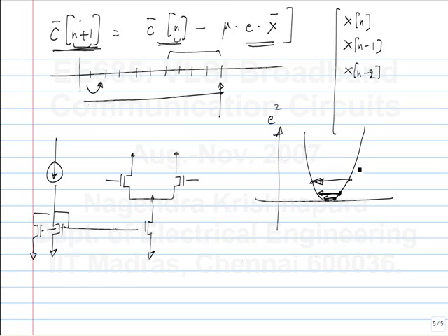Yeah, so you can do that. But what is the limitation there? To reduce the value of mu, you simply have to have more steps, right? Because in this case, I go from having one transistor to two transistors, three transistors and so on. So the step size is limited by how many pieces I have split this transistor into. I can keep on splitting it into more and more pieces, but beyond some point it becomes not practical. In fact, with this kind of realization, maybe 5 or 6 bits is the maximum.